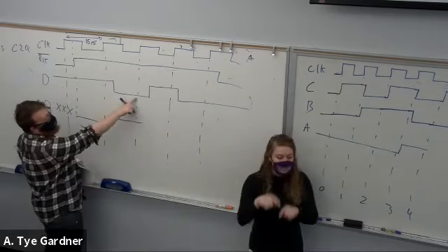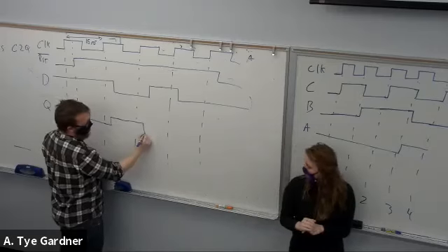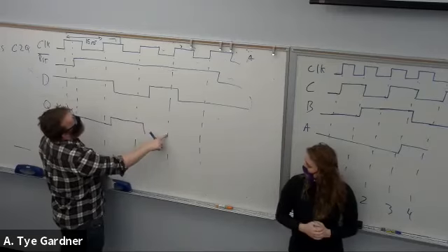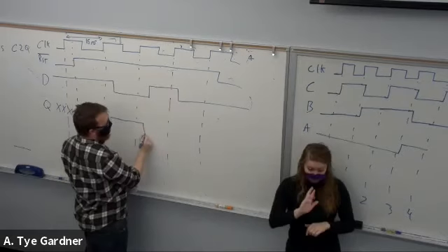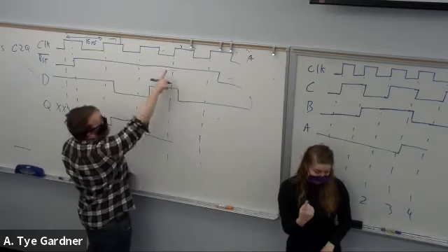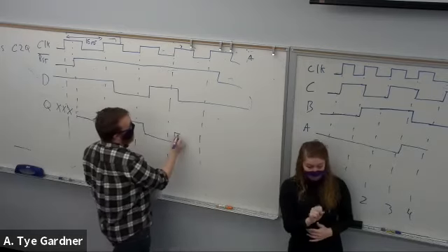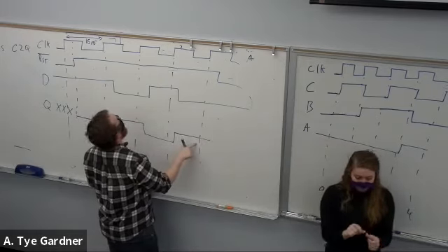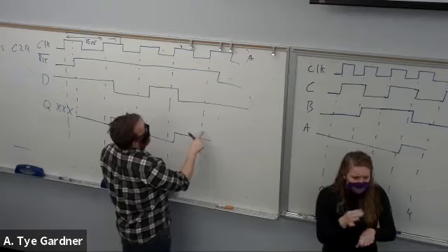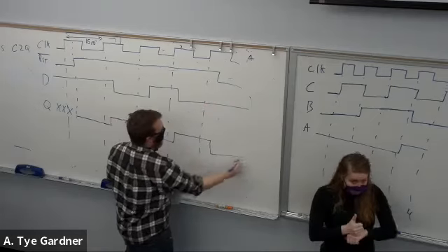Rising edge of clock happens, we're at 0. We drop to 0 there. Fourth clock happens, still not resetting, D is 1. So fourth clock, wait 4 nanoseconds, switch to 1. We'll go until 4 nanoseconds after the, what is this, 5th clock. And then still not resetting, back to 0. Ta-da.